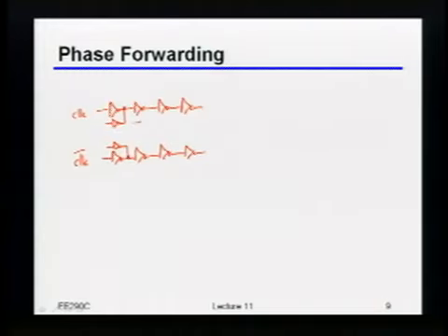At every one of those stages, we had another inverter that was going to enforce that we got the right differential condition. What we did last time was the input of this inverter here, we tied to the output of that inverter. But that was guaranteeing that things slowed down. It was guaranteeing that we had to fight this inverter to actually move forward in time.